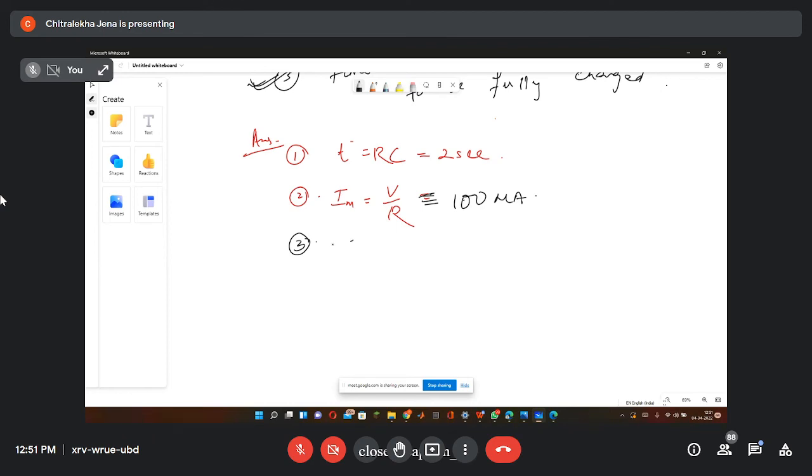Ma'am, dVc by dt. Who is answering? Ma'am, Satya. Same Satya, the rest of the students are not there. Ma'am, it is equal to V by RC. V by how much? RC. V by RC. How much is it coming? It will become 50 volt per second. Okay. Yes, ma'am. Number 4.